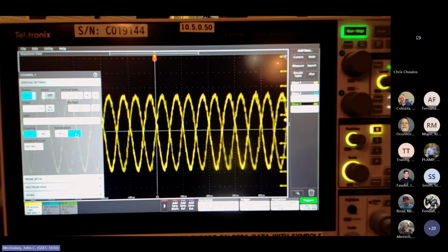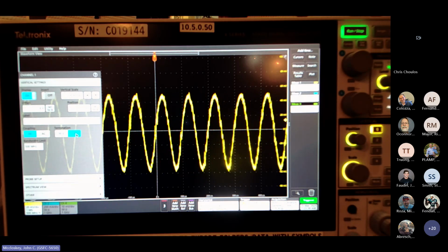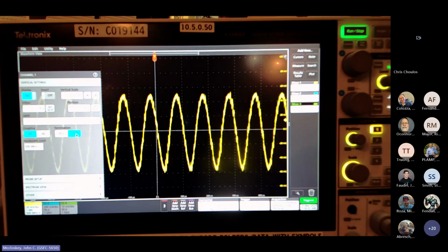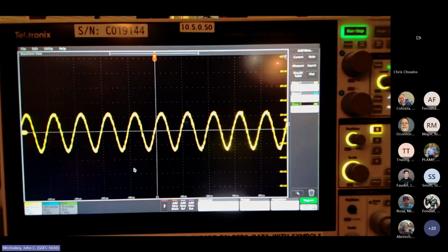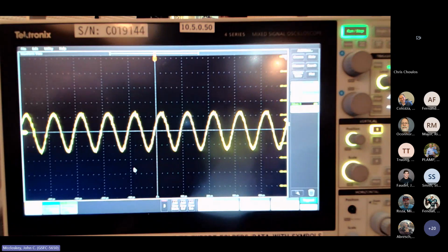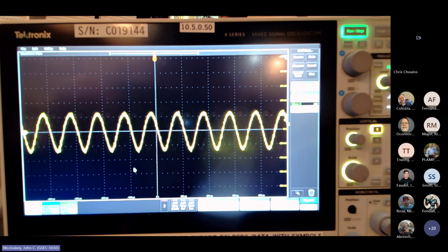So you would expect it to essentially double. And at these low frequencies, your source impedance is dominated by the magnetizing inductance, so it's very low. So it will essentially double, and that's what we're seeing here. We went from roughly 18 to roughly 36 millivolts RMS. So going back to 50 ohms, what you're doing with this calibration step is establishing a maximum open circuit potential and a short circuit current. You get both of those with some fixed source impedance.